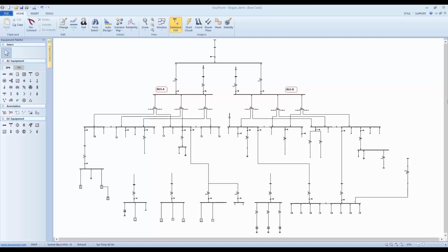Finally, when it comes time for QC, there's an additional benefit. Instead of handing off your model along with a reference to a folder and a bunch of papers to whoever might be checking your model, you're now handing off just the model, and all of the pictures or data that you've gathered, the notes that you've taken in the field, are already embedded in the model. They're associated with the correct pieces of equipment. And so when somebody has a question about that transformer nameplate or those settings on that breaker, they can simply double click, look, confirm, and you've got what we think is a better process for gathering data and getting into your model so you can get quicker to analysis.